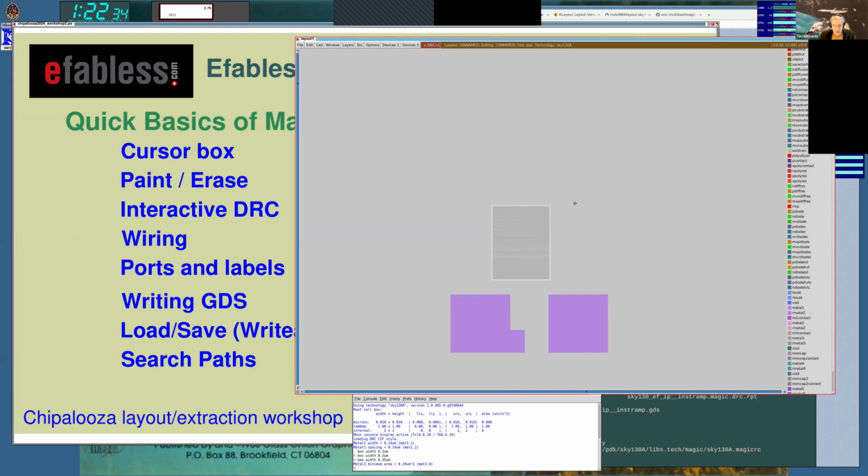So I'm going to go to the wire tool, press the space bar. The space bar switches between tools. So I can go from the box tool, press the space bar once, and I'm in the wiring tool. That just changes all the key bindings of the mouse buttons so that now when I use the mouse buttons, I can do wiring. If I want to get back to the box tool, I can cycle through the different tools with the space bar. So there are a couple other tools, a pick tool. This goes back to the box tool. Once again, I come back to the wiring tool.